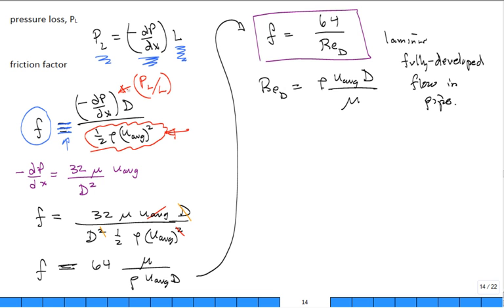But okay, you recall from our analysis that the maximum speed, the viscosity, diameter squared is related to negative dP dx. You put that into the friction factor definition for laminar flow. This is only for laminar. This is always, that's the definition of the friction factor. But you put in what is dP dx for laminar flow, and you work out a very simple relation. Box it. Remember it. It says that the friction factor for fully developed laminar flow is equal to 64 over the Reynolds number for fully developed laminar flow in a pipe.